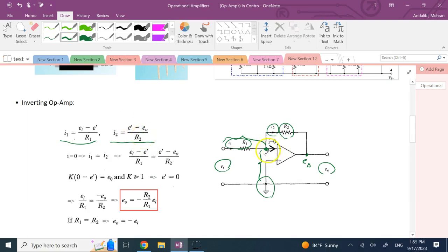Now, as I said, the input currents into the terminals of op amps are very small. So here, you see I have a node. I1 goes in, and then this I and this I2 go out. So I1 is equal to I plus I2. But this I that goes into the terminal is very, very small. We practically say it's approximately 0. That means I1 should be equal to what? I2. So all of this I1 goes to this branch I2. If that's the case, it means these two ratios are equal.